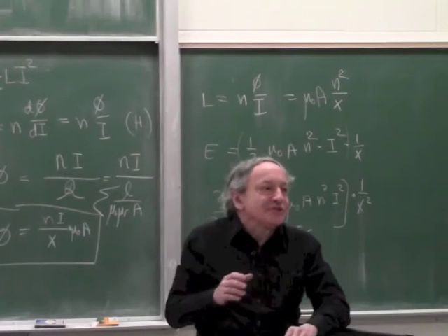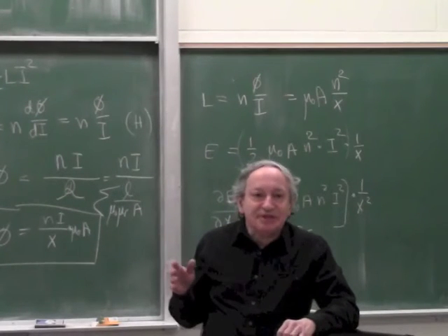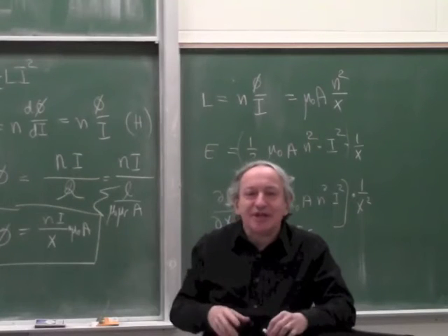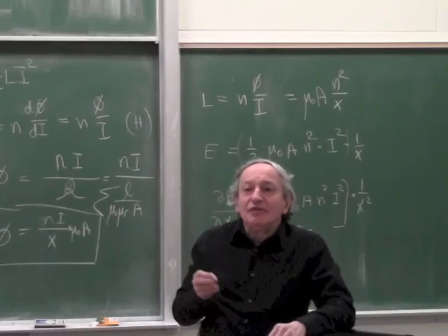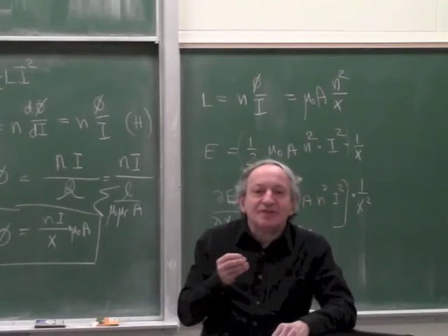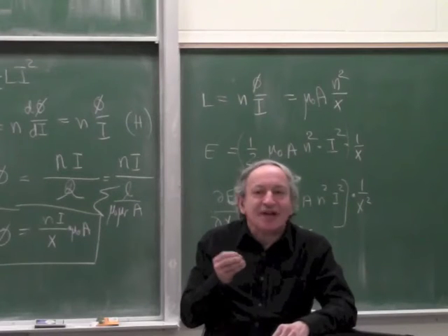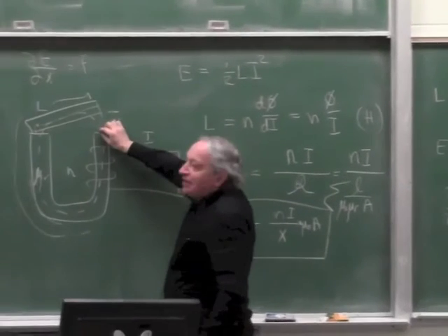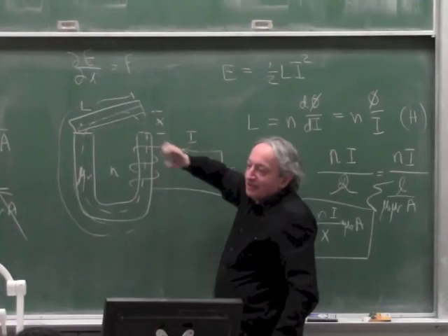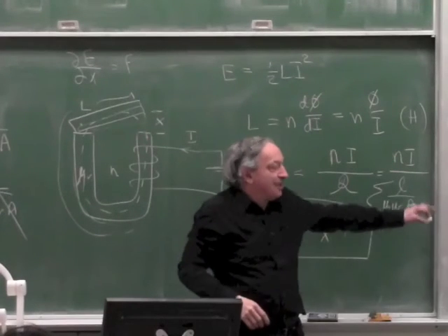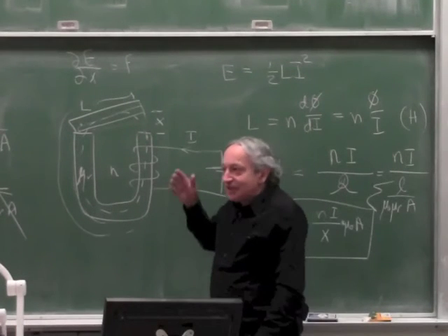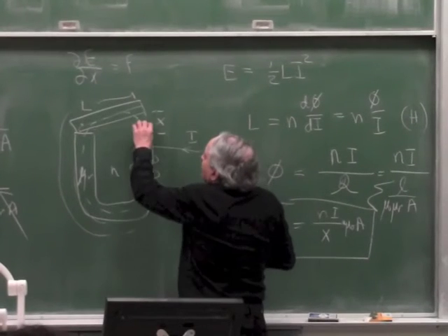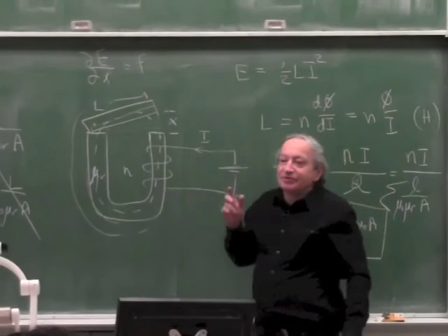The limit of all servo systems is stability. We harped on it long enough, right? The stability of phase shift, you have too much gain, it oscillates. If you have variable gain, you have to design your servo system for the highest gain. Like when this comes near closure, the gain becomes infinite actually, right? According, at least by the approximation we have, the gain will become infinite. But let's say it's not infinite, you control the gap, so you only allow the gap to go to here, but the gain becomes very high.